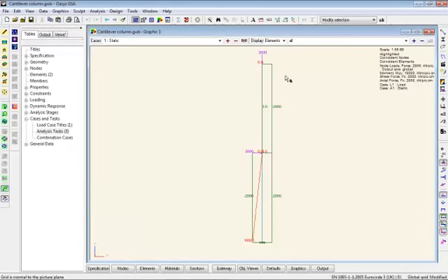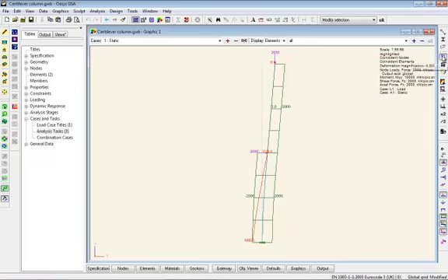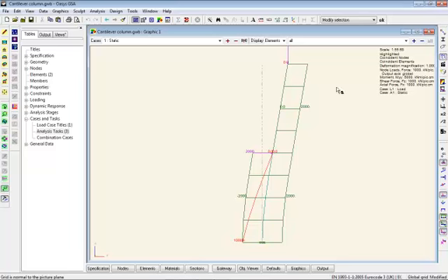Okay, so applied load of axial load of 2000, getting axial load of 2000 all the way down, horizontal load of 2000, which means we get a 2000 kilonewton shear and a 10,000 kilonewton bending moments on this column section. But it is deflecting over a reasonable amount.